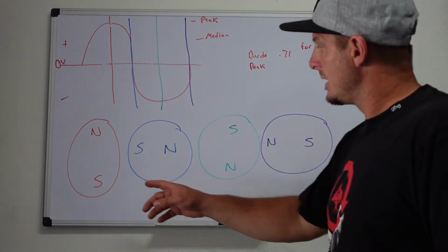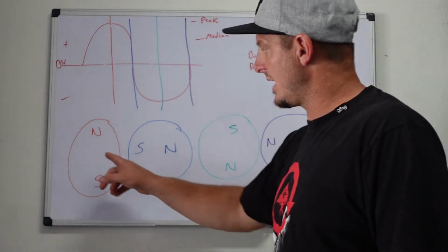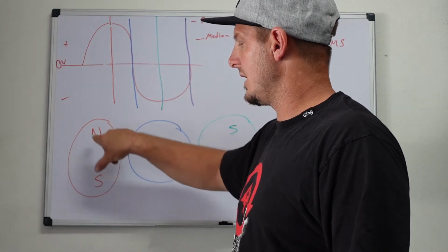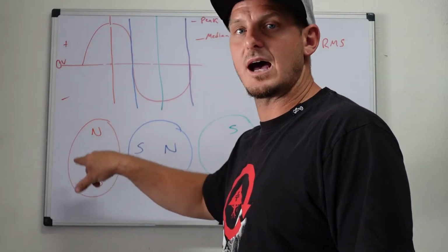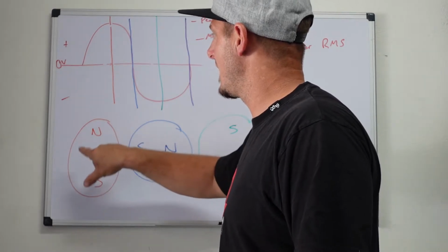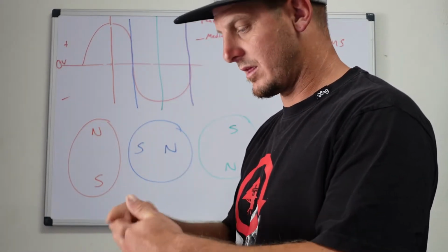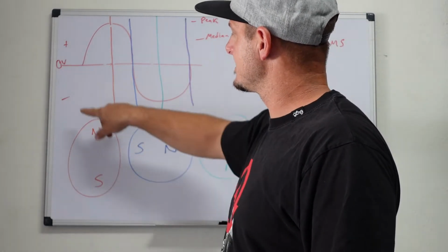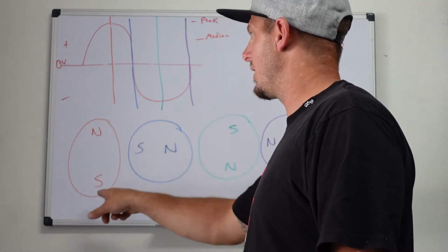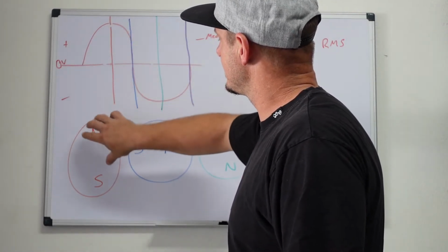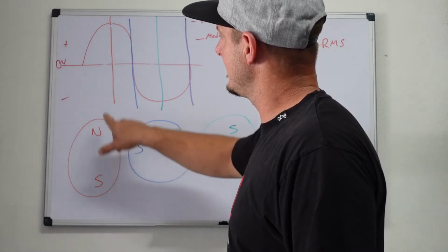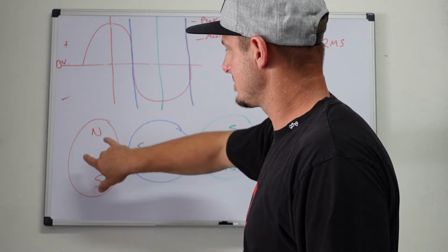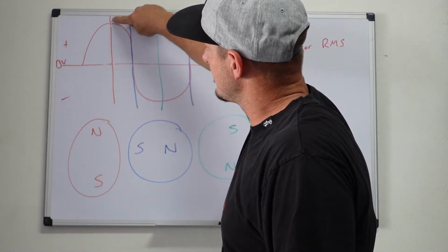Now, the way power is produced is you'll have a conductor inside of here. This will be a set of magnets that the conductor will actually spin inside, and it will be creating voltage on that conductor, right? So as it's spinning north-south, imagine it's spinning clockwise, okay? As it's spinning clockwise and it gets to this next state here, it turns a quarter turn, that then gets us to right here.